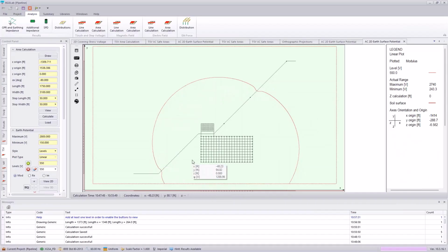Within this zone, if we have any metallic structures crossing this line, that means we can have transfer voltage into or out of this system. Those types of recipients would be things that we would look into. And this is a plot that you can export out to DXF, because there are some countries where you need to specify within 1,000 volts, these types of entities need to be evaluated, or 300 volts. This is one methodology that you can do that.